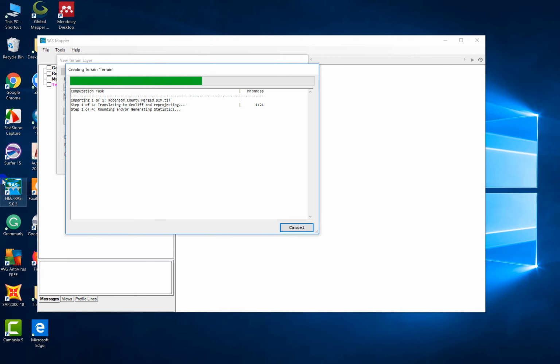That's great. And after defining our 2D flood area and our boundary conditions, we will assign something called a hydrograph. Are you familiar with the term? Hydrograph. Yeah, it's discharge with time, Q with time. In case of river flooding, the river is in a normal condition, but at the flood it goes very, very high and then drops with time. So this is the hazard discharge.